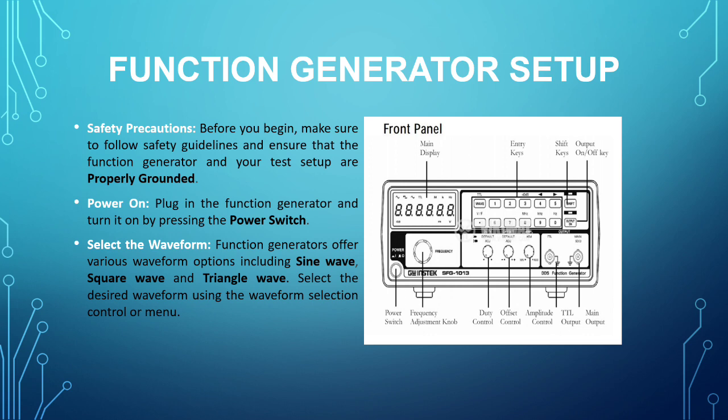Function generator setup. First, before you begin, make sure to follow safety guidelines and ensure that the function generator and your test setup are properly grounded. Next, plug in the function generator and turn it on by pressing the power switch.